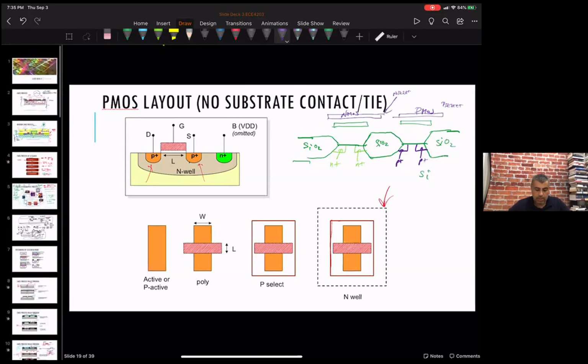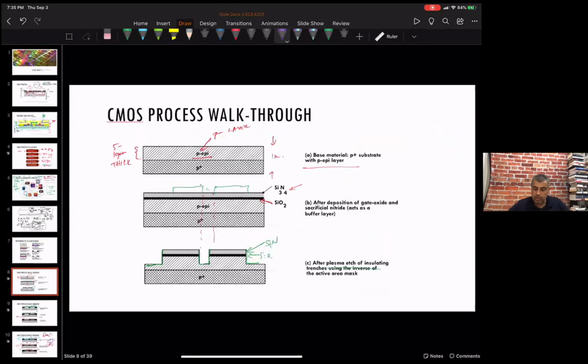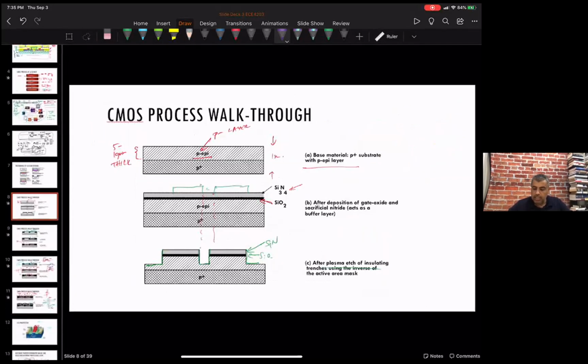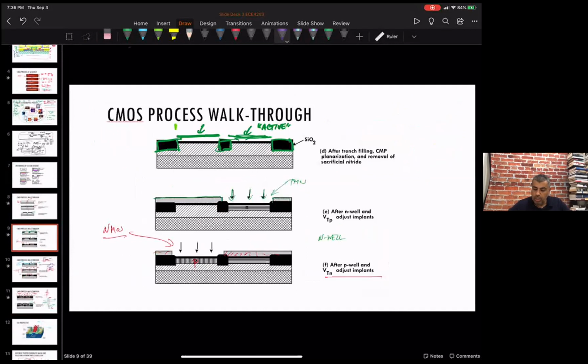So how do I explain this further? Let me say this another way. Going through these steps, again, the active layer basically defines where there are active components, which are NMOSFETs and PMOSFETs, okay? Then the N select and P select are two different layers that determine whether you're getting an NMOSFET or a PMOSFET in those cuts.